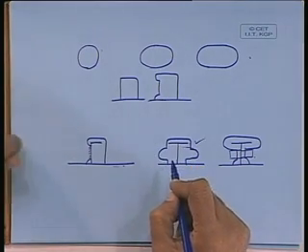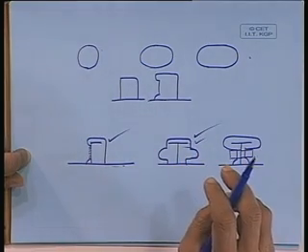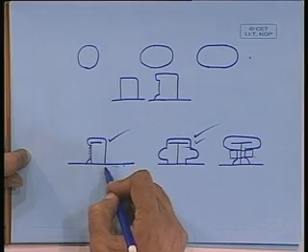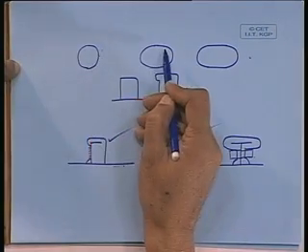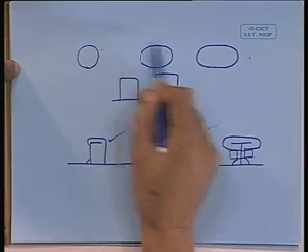If you open Lloyd's Register of Shipping's structural book, you will find this opening. Now you see what is the complicated shape here. These are practically required, and theoretical result is available only for these two, a circular hole and elliptical hole.